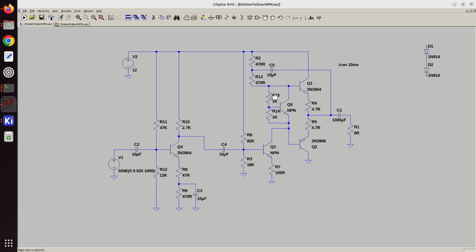The difference is if we make one of these a variable resistor, we can adjust the voltage here. So it could be like 1.2 or 1.8, and that's important because you barely want to turn these on, just enough to have them operating in the linear region. If you turn them on too hard, you're going to be wasting a lot of current if there's no input signal. There's still a lot of current going down here.